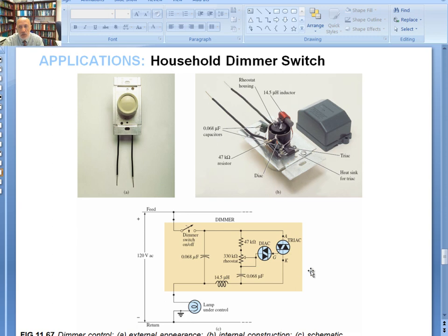But every time the switching is happening with a triac, the SCR, there's some high frequency generated. The inductance, as we said, acts like an open circuit at high frequency because its impedance is omega L. At a high frequency, omega is extremely large, so the reactance, which is the impedance of the inductance, will be extremely high, and therefore will block all the high frequency noises coming in from the triac, from the switching circuits, the control switch right here.